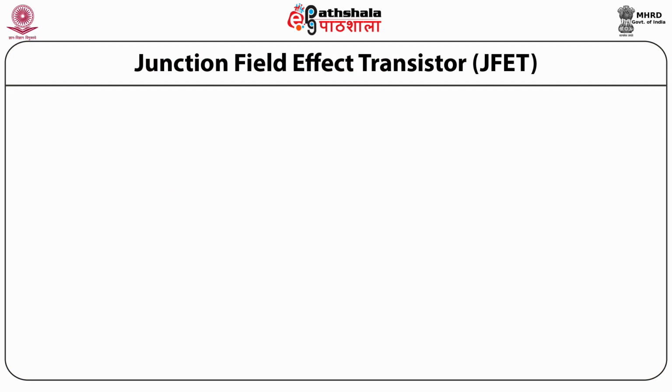There are several terminals in JFET. The terminal through which majority carriers enter the bar and the terminal through which they leave are known as source and drain respectively. And the heavily doped region on the two sides is known as the gate. In the junction field effect transistor, the junction is reverse biased. As a result, a depletion region extends into the bar. By changing the gate to source voltage, the depletion width can be controlled. So the effective cross-sectional area decreases with increasing reverse bias. So the drain current is a function of the gate to source voltage. Nowadays, JFET is obsolete. Its applications are limited to circuit designing, where it can be used as an amplifier and as a switch both.